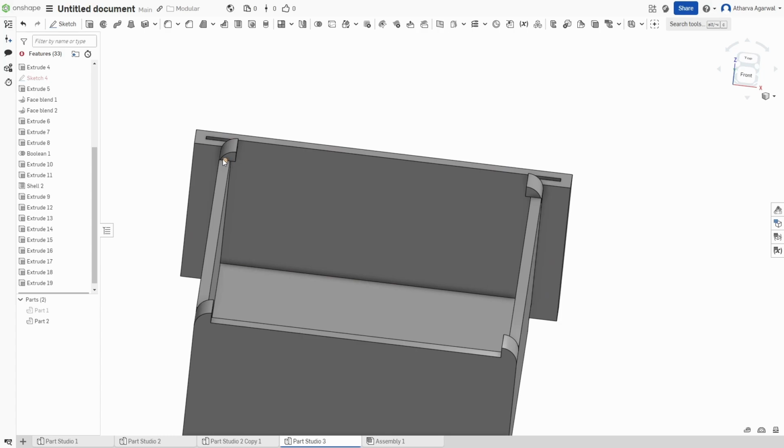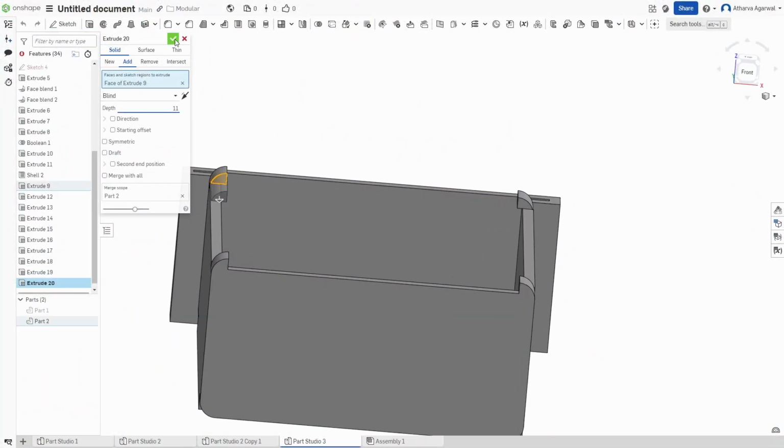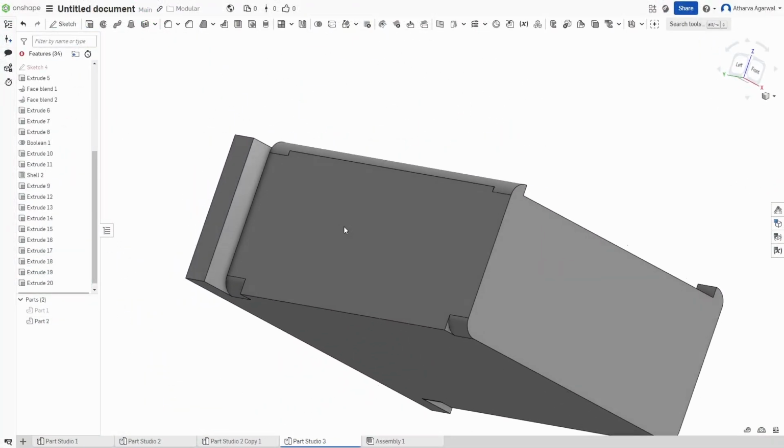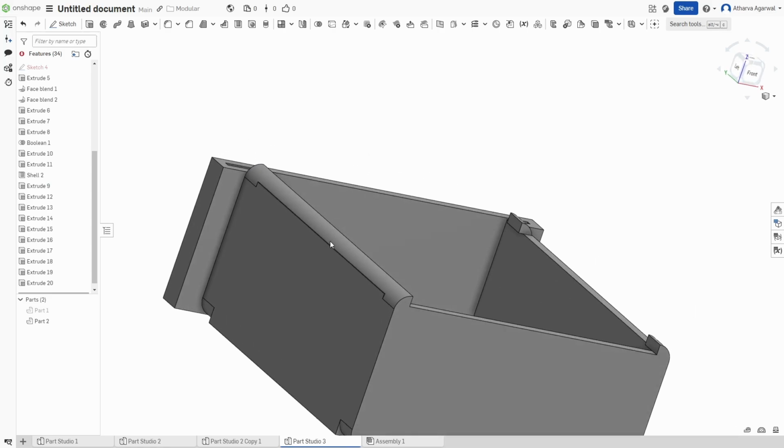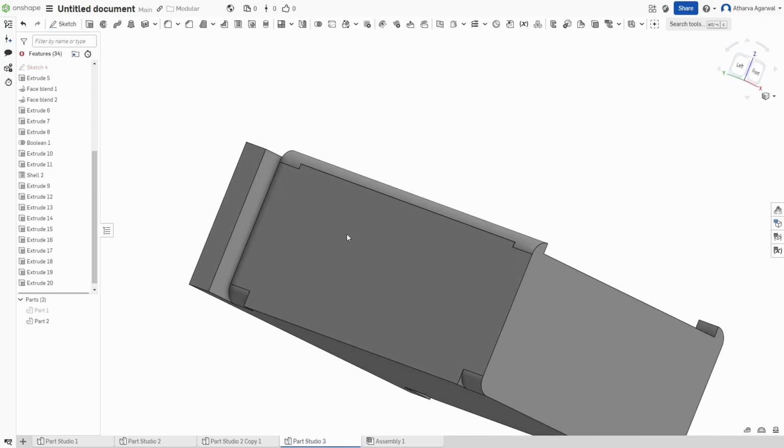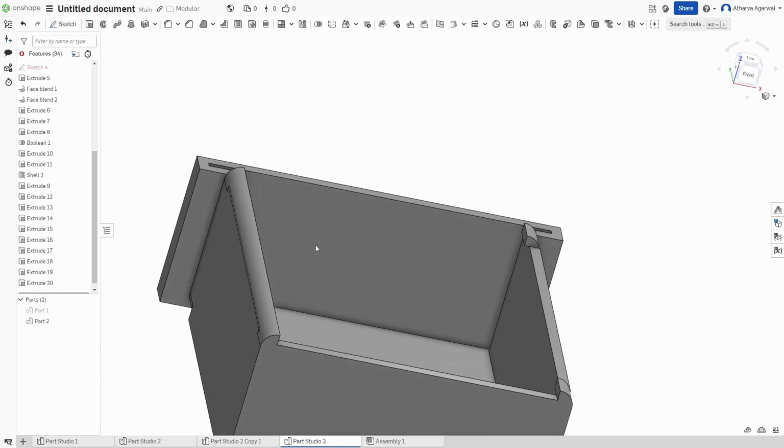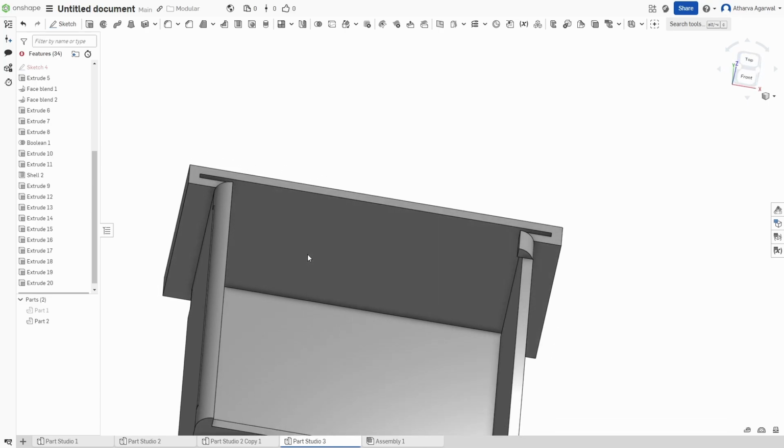A few minutes later, I can see that little overhang area. What I'm going to do is add another extrusion on the plane I just selected, and this would create a much smoother insert experience. I've done this on both sides. I specifically put 11 for mine, accounting for the 1 cm I removed at the front originally, and then also the 1 cm size of those overhangs. So it gave that clean look you can see there.